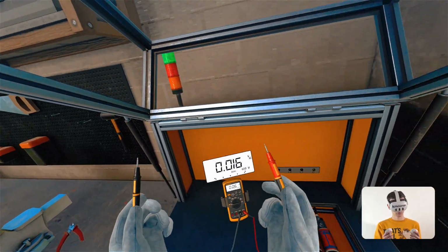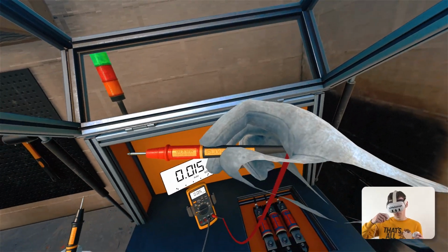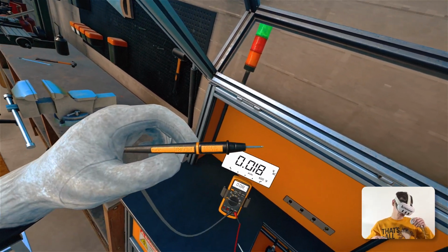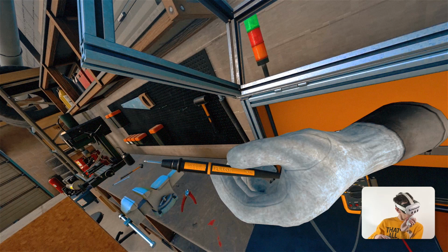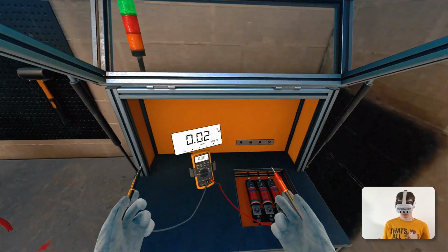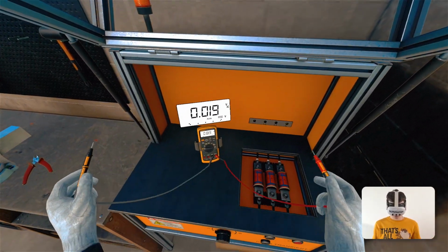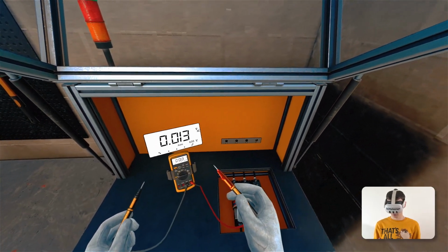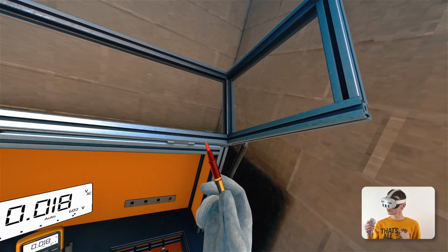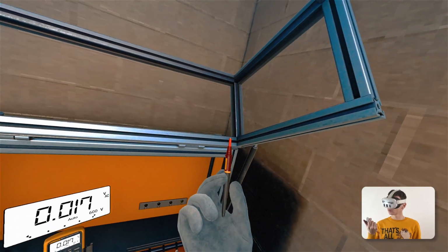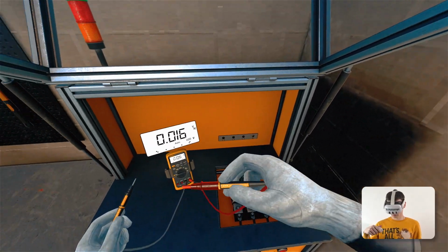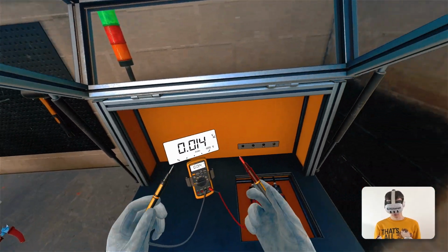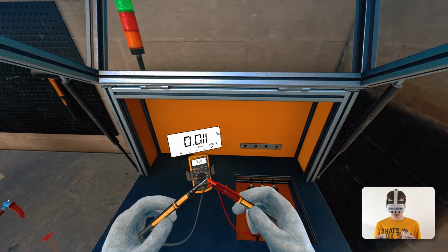These unique leads offer adjustable length test tips, allowing you to tailor the probe tip length to your measurement environment's needs. It's crucial to remember that with the insulator extended, the meter lead is rated for CAT 3 up to 1000 volts and CAT 4 up to 600 volts. However, with the insulator retracted, the meter lead is only rated for CAT 2 circuits, such as outlets and appliances. Maintaining proper insulation and alignment is key for accurate and secure testing.